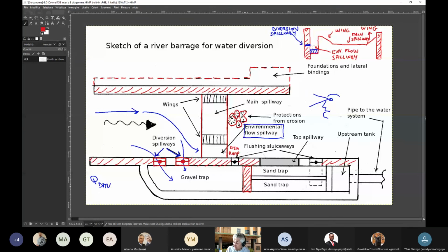In particular for the sand trap, we don't want to exceed a meter of depth, okay? And in this case, the step between the two can be 50 centimeters. And that's fine. Also the downstream end of the sand trap is closed with a step, okay? We will discuss later what is after this latter step. It's what is called the upstream tank. We will discuss it later, okay?